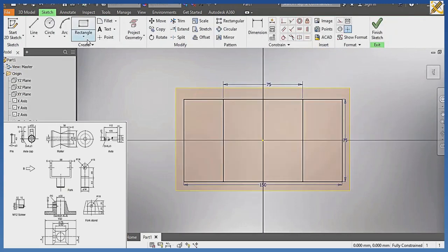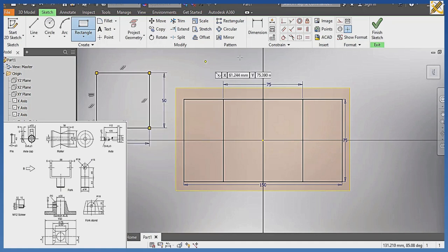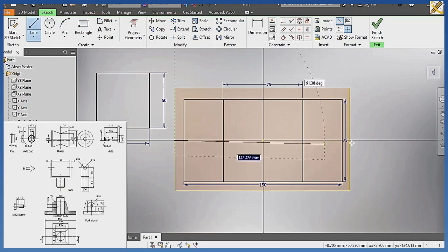After creating that new sketch, I'm going to pick my rectangle. I am producing a rectangle of side 50 by 50. Enter. I'm going to pick my hidden line, pick a line from this area and draw this towards the midpoint right there, then pick my line also vertically.